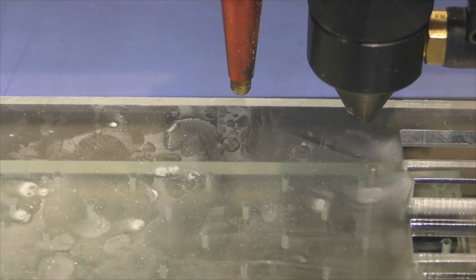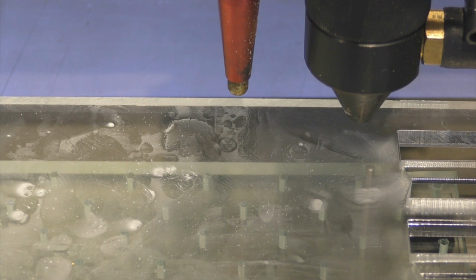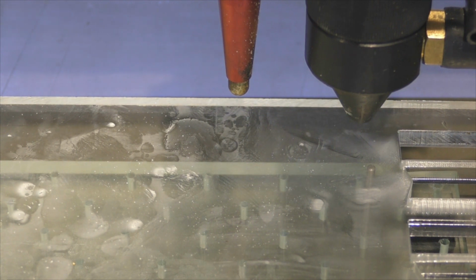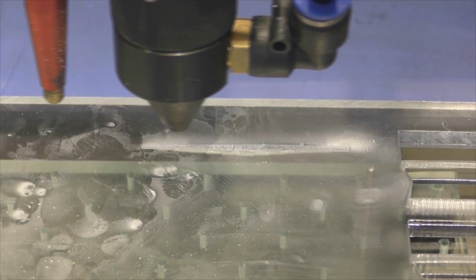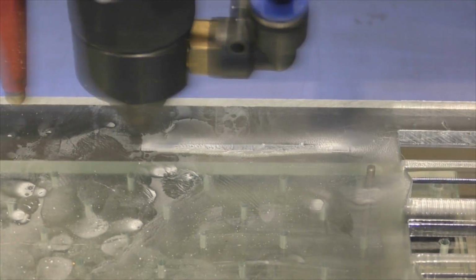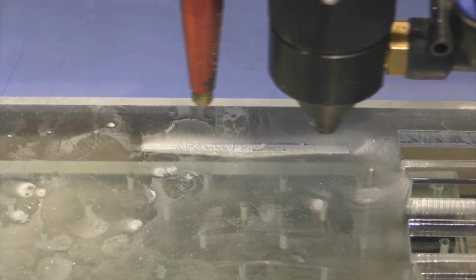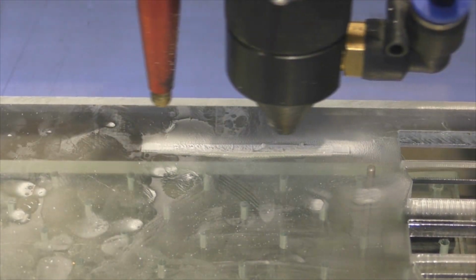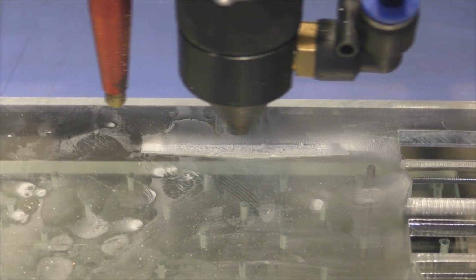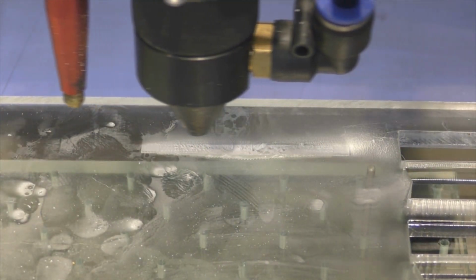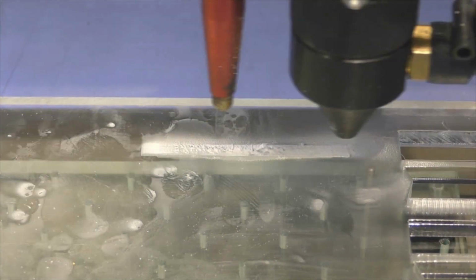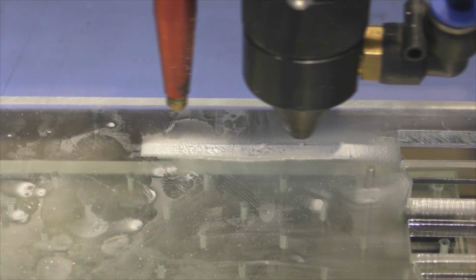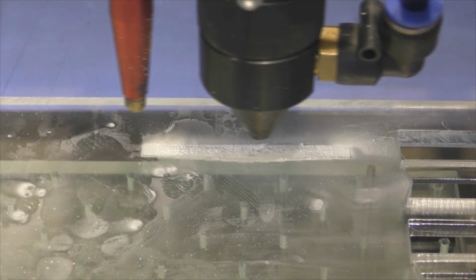Okay, now you can see from the black nozzle that we're on the light blade machine now. I think this will run in the opposite direction. The scanning will run in the opposite direction, but it's still single scan. Even on this machine, which is a different tube, you can hear that pre-ionization taking place at the end of each end of the stroke. Now it sounds like a strange airflow that's taking place just at the end of the stroke as the cut gets shallower, but it's not. And again, it looks as though it's taking place over the first and last two steps.